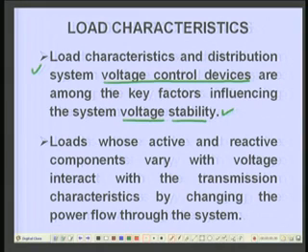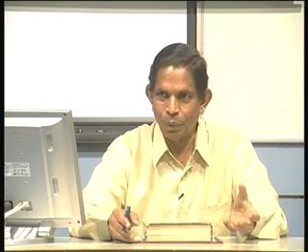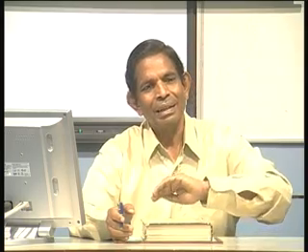Those who have done some studies of the power system, and want to account for voltage dependent loads, if you perform load flow analysis considering the voltage dependent loads, then the solution of the load flow will be different than a case where you consider constant PQ loads, because the moment the load at a particular bus depends upon the applied voltage, the resultant voltage will depend upon the composite characteristic of the transmission line and the load characteristic.